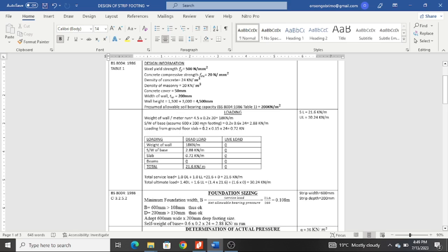And then after determining this, we came and added these loads. From observation, you can realize all these are dead loads. We don't have any live loads here, and this is basically the explanation. This strip was placed where we had a framed structure, so most of the structure's loading was distributed to the foundation via the columns and then to the pad footings. So our strip was only distributing loads from the ground floor masonry wall to the substructure masonry wall to the strip footing.